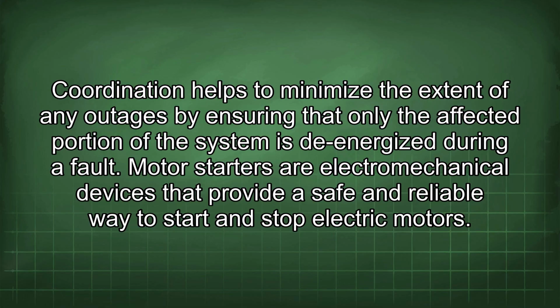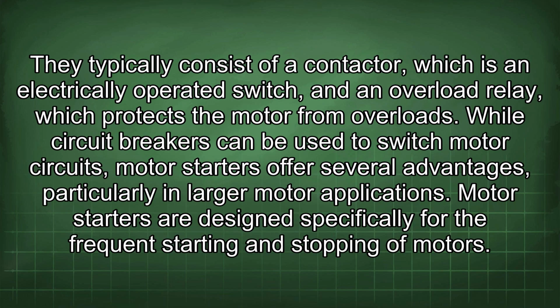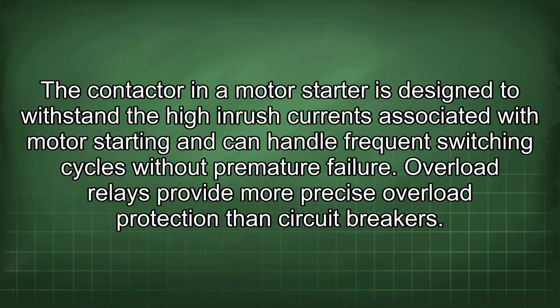Motor starters are electromechanical devices that provide a safe and reliable way to start and stop electric motors. They typically consist of a contactor, which is an electrically operated switch, and an overload relay, which protects the motor from overloads. While circuit breakers can be used to switch motor circuits, motor starters offer several advantages, particularly in larger motor applications. Motor starters are designed specifically for the frequent starting and stopping of motors. The contactor in a motor starter is designed to withstand the high inrush currents associated with motor starting and can handle frequent switching cycles without premature failure.